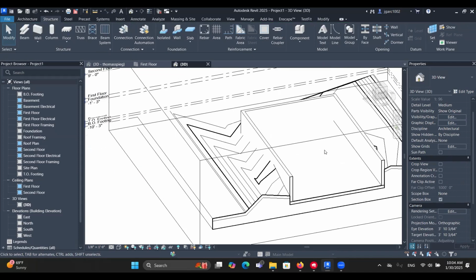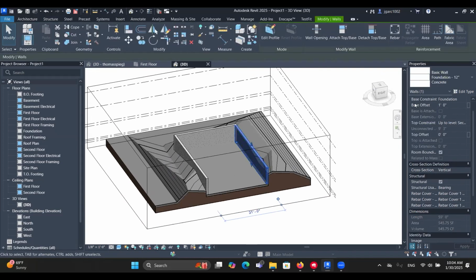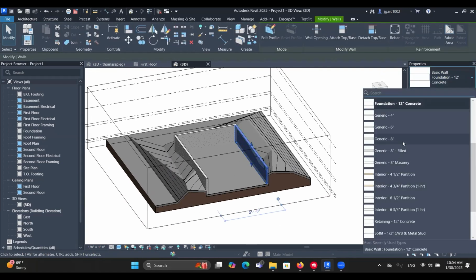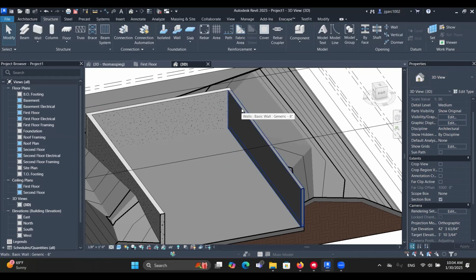Okay. Now, cloning materials of a wall. Say this wall, for some reason you did it as 8. You can save some time if you do this command. I'm going to post it right now. So MA equals match properties. You should be familiar with this.